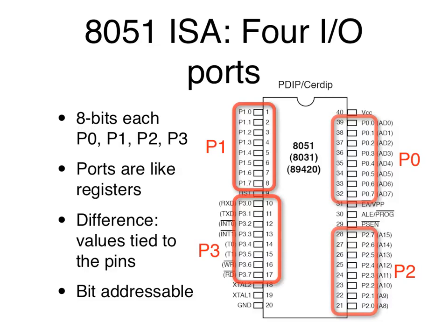And these are just the original 8051 definition. In newer chips like the CC2540, which we'll be using, there are many, many other secondary functions you can possibly use. Okay, so you may have to configure your microcontroller to say, oh, I don't want it to be a general purpose I/O port. I want it to be something else. How do you do that? Again, through special function registers. Okay, so you need to know what SFR to use to let you choose one or the other function.